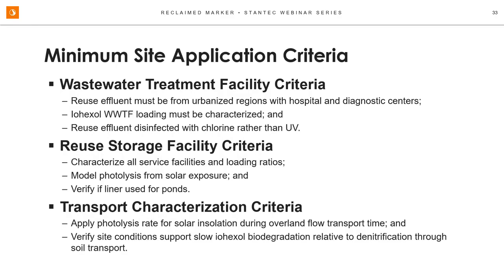But if you end up with a situation where it's loaded and not consistently used and it stores in there for many, many days, and then again, it depends on the depth and the sunlight penetration and such, you may have a situation where you're susceptible to too much photolysis because of the manner in which the reuse effluent is stored. Obviously, if it's stored in a covered facility, it's a different situation, or if it's continually withdrawn at almost the same rate at which it's filled, that's a different situation that might work.